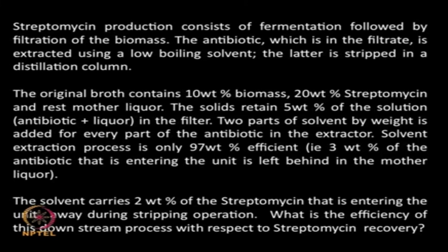Then it goes to the extractor where you are adding some solvent and extracting your antibiotic. The extraction is not very efficient, because 3 weight percent of the antibiotic that is entering the unit is left behind in the mother liquor. That means only 97 weight percent of the antibiotic entering the extractor is taken up by the solvent and 3 weight percent is left behind by the mother liquor. So we have lost 3% here.